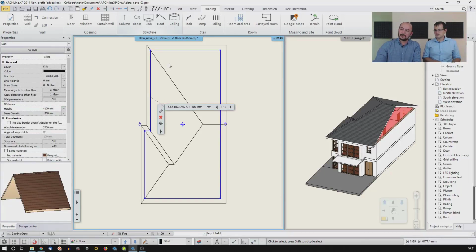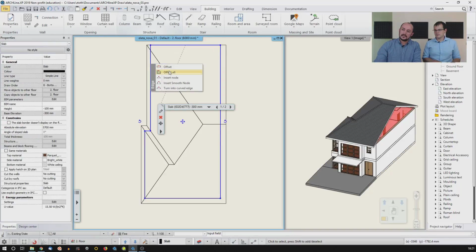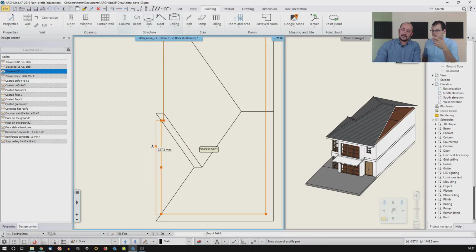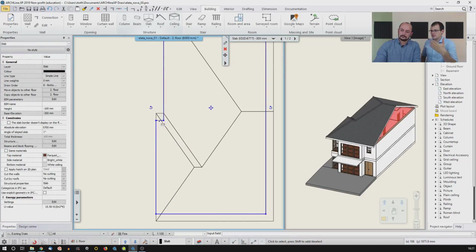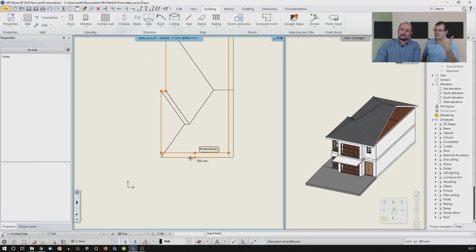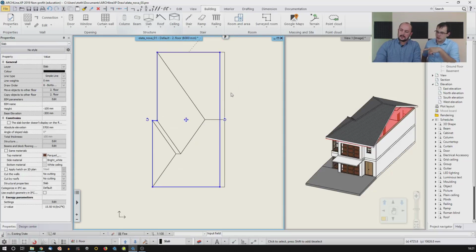I click on the slab contour and I click on the edges and I use the offset to match the edge of this. So now you're highlighting the slab that you just worked with. Now it's easy to snap to the roof and you just extend it. We could be using the offset command, but for every single roof plane you have different values, so we can't use that. But now we can use the slab as a reference to offset back the roof planes, right? Yeah. So I can click on the roof.